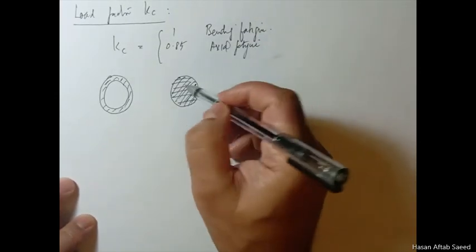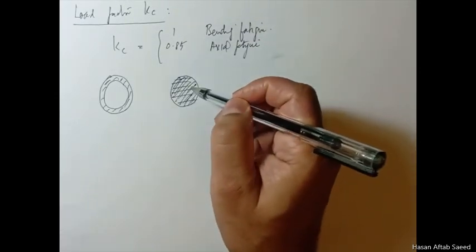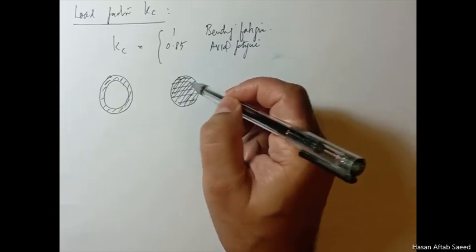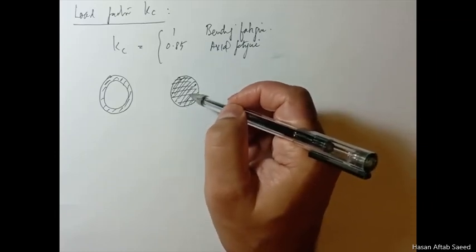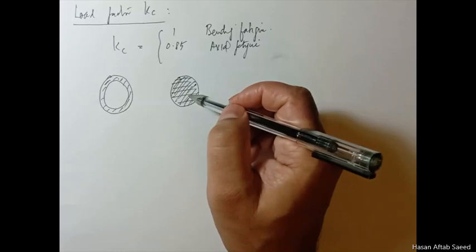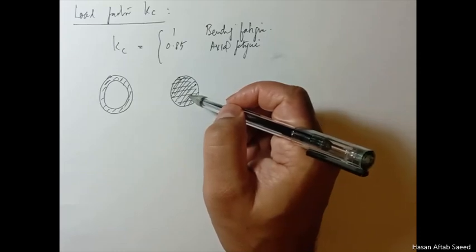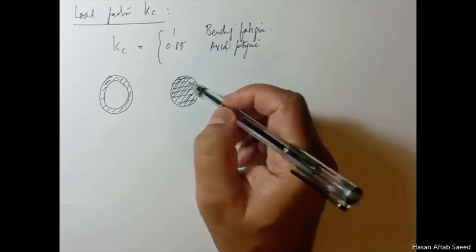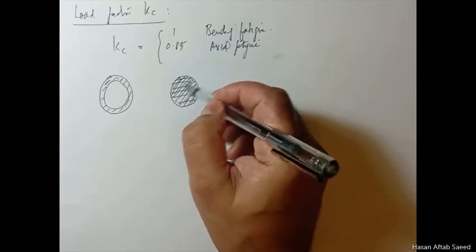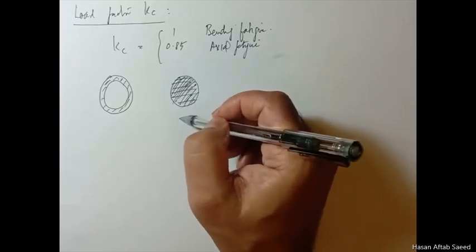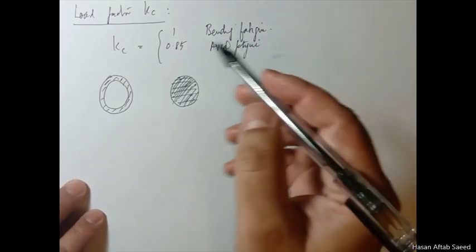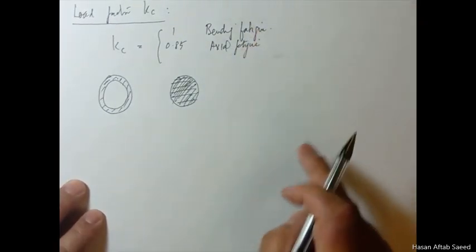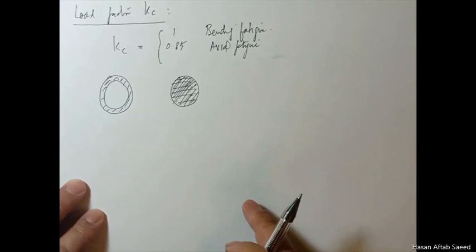So what happens is that the likelihood of potential cracks, again we are talking about probabilities, that grow on to become large and then become critical is larger here than this. So here you are talking about more probability of failure, early probability of failure. Now, this might give an impression that axial fatigue is more dangerous than bending fatigue.